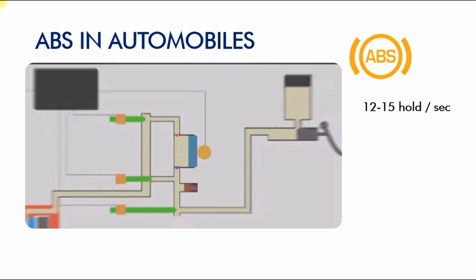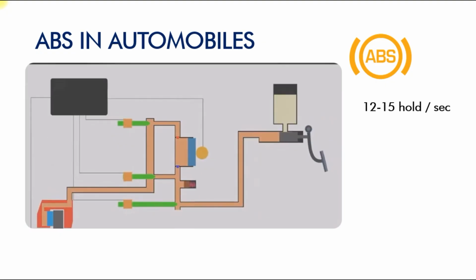So at the moment when you apply the brake, the wheel speed as well as the engine speed will be compared. There will be a drastic change, right? When you immediately apply the brake, the odometer will slowly reduce its value, and the speed sensor can detect the immediate arrest in speed. So there is a clue for the entire intelligent system behind this ABS. If there is a drastic change between the odometer and the wheel sensor, it will start applying the ABS.